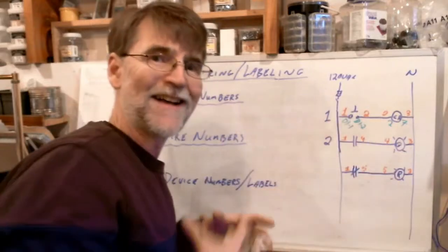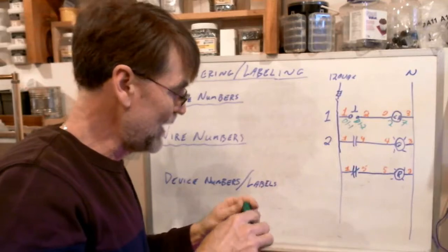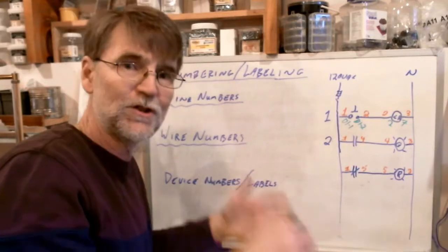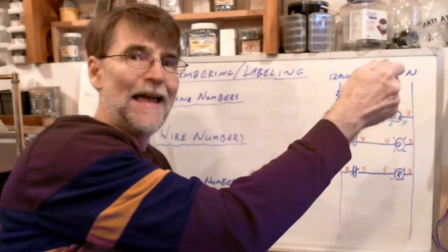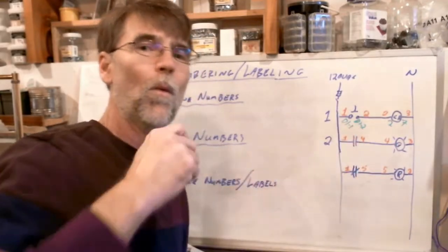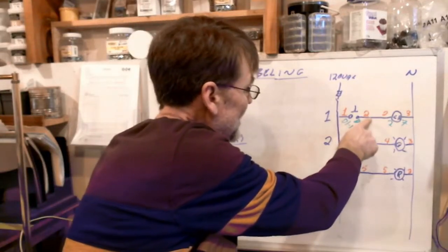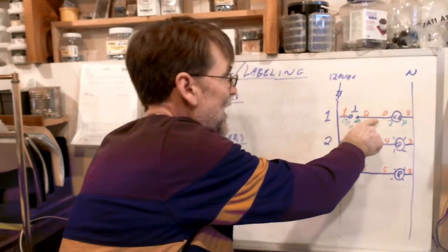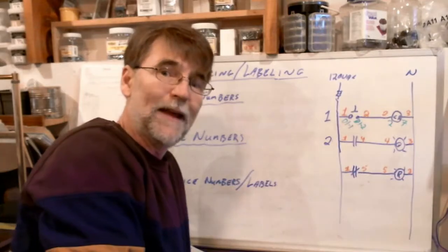This is information that you guys are going to get into, and you're going to get really comfortable with this. But here's the point. When you're working at your lab station, trying to decide what to do with a particular wire, say I'm holding a wire in my hand and I'm going to connect that wire to D12. What do I do with the other end of that wire? Well, if you've connected one end of that wire to D12, then label that wire 2 and attach the other end of wire number 2 to pin 2 of the cube relay.